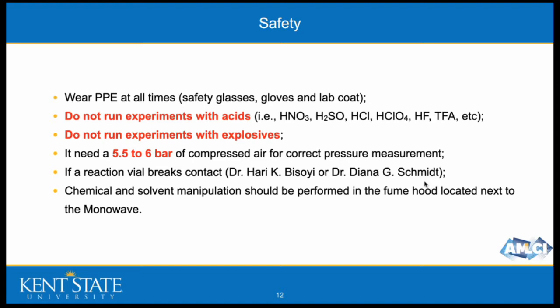The machine needs to be under a constant pressure of compressed air. It should be between 5.5 to 6 bar, and you shouldn't mess with these setups. So do not play with the flow regulator. Leave everything as it is.